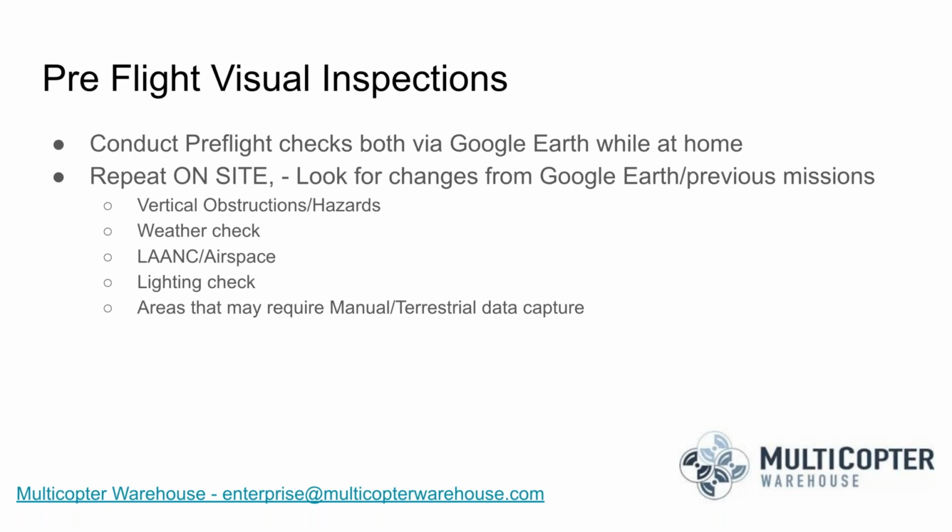In the fast mode, it simply uploads the waypoints for each end of the flight lines, and the drone will fly along that flight line and it will get a command from the controller at a set time, take a picture now, take a picture now. And so if you do have some kind of communication loss with your drone in the Android version of the app, you may have some dropped images. But the iOS version does allow for that safe capture mode and have the drone hover in place. Of course, that will slow down your data capture because it takes a little bit longer for the drone to start and stop each photo.